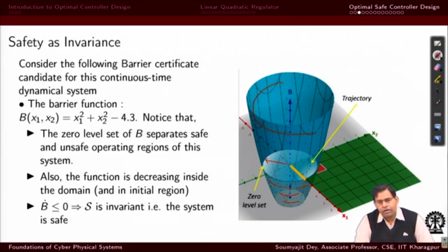Now, if you remember, why is this a valid barrier function? Because ideally we could have allowed the system to go here, here, everywhere, but not here, right. We are taking a subset of this allowed safe set and creating a barrier function in that subset, and that is my requirement. I am free to choose the subset, as long as nobody is asking why my subset is small. It could also capture this, but then it may not be a continuous convex shape, right. So, as long as I am here, it is still safe. As long as I am below, it is still safe.